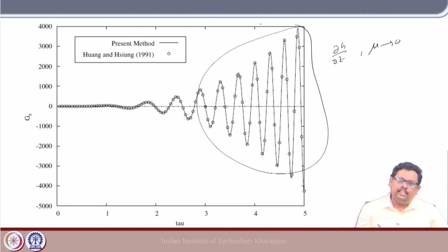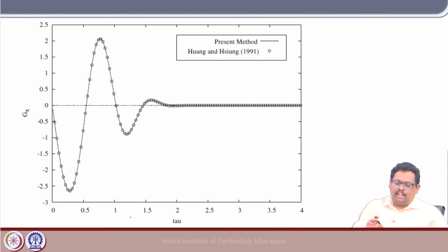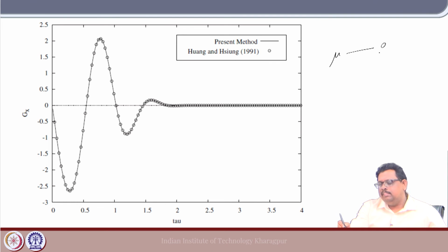Now, that is the typical problem of the time domain panel method. The solution sometimes becomes divergent, the solution does not come out correctly; numerical instability occurs because of these things. Otherwise, if mu is somewhere away from 0, then you can see a very nice convergent solution. So you have to remember that this sometimes leads to some kind of instability.